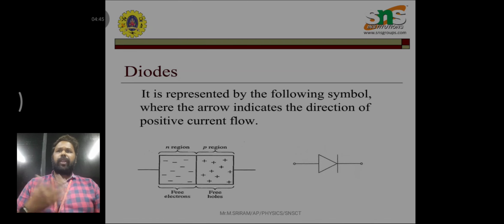And Schottky diode. It has a lower forward voltage than other silicon PN junction diodes. The drop will be seen at low current. The voltage ranges between 0.15 to 0.4 volt. These are constructed differently in order to obtain better performance. Schottky diodes are highly used in rectifier applications.